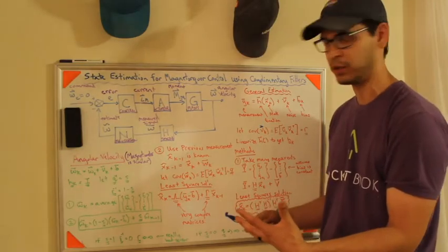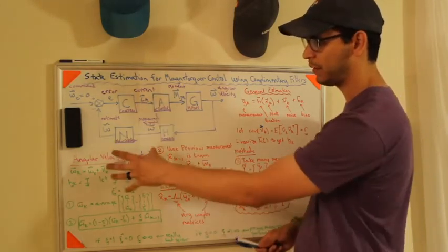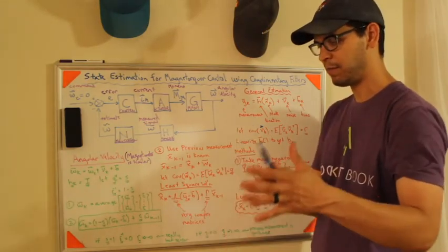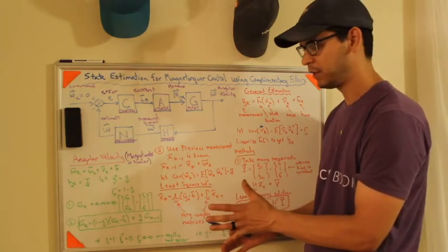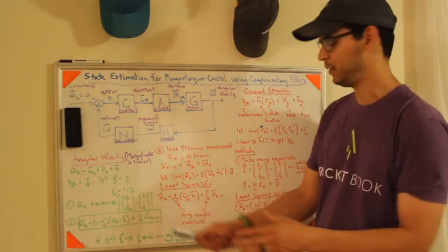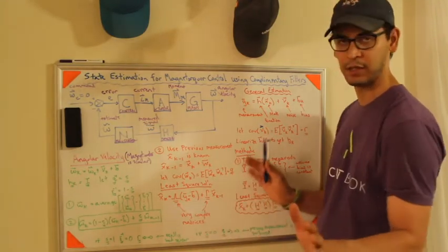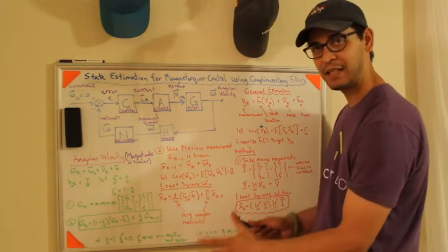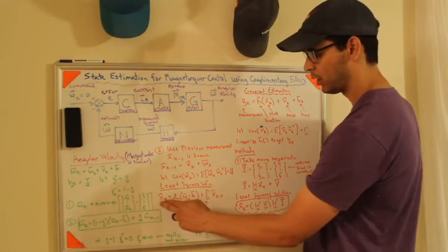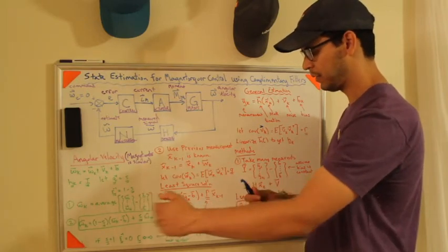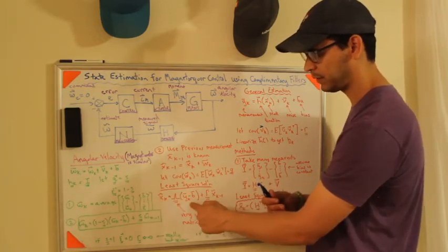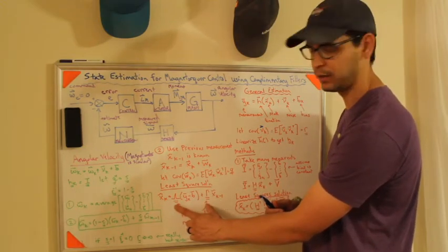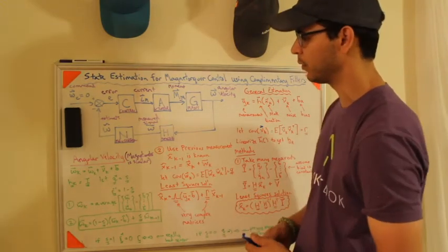I don't think it's important to learn them because when you apply these to angular velocity measurements and magnetometer measurements, you end up making so many simplifications that the final solution is way easier than these matrices were in the first place. But again, the main takeaway is your next estimate is your previous estimate plus your current measurement with these two factors included.